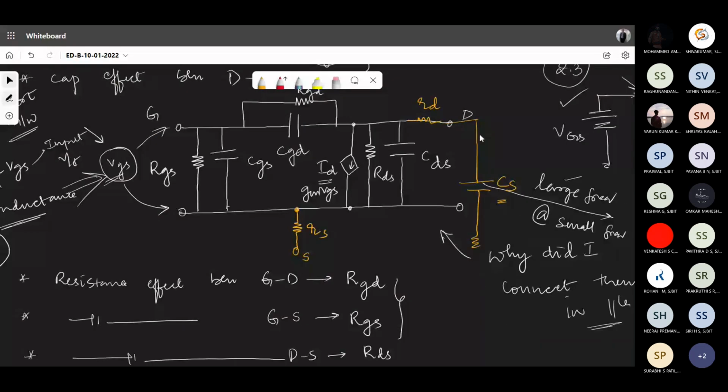And that is what is included here. It comes between the drain and not the source, but the ground point. That source becomes the ground point because source is common here. So that is what is CS. So please understand, whatever we had earlier, everything is retained as it is, except that two components of resistance and one component of capacitance are coming into picture because of that new type of construction. It is also called the planar construction. It is called the planar FET.